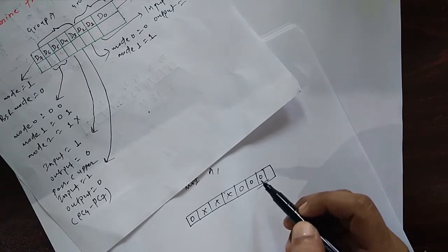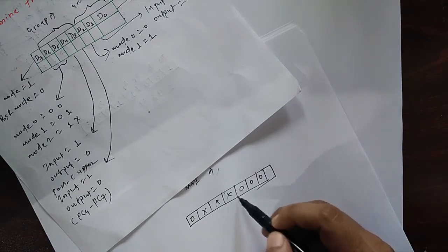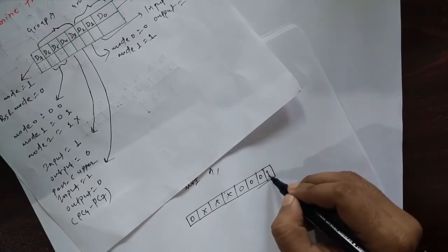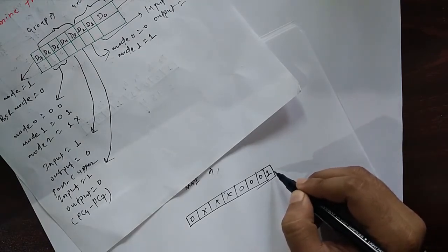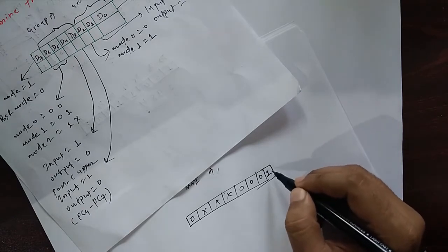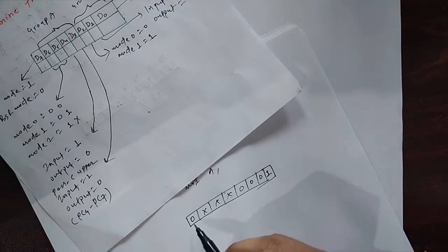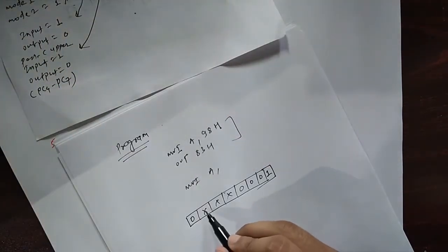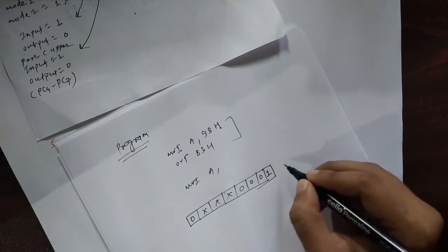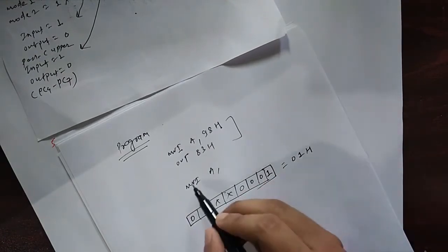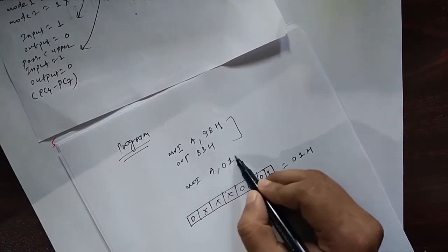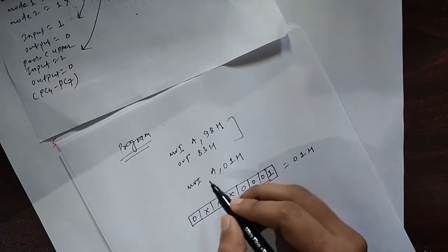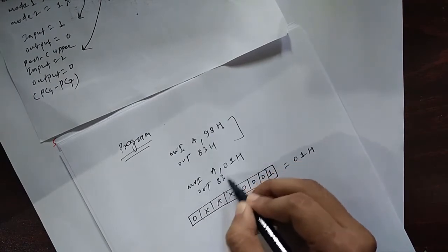So now I guess you have an idea what to write in these 3 fields. And if you are setting, then we write 1, otherwise 0. If we are resetting, then we write 0 here. So this is the control word for setting PC naught. If we consider don't care as 0, then this will be 01H. So MVI A, 01H, and then we need to output it from control register, so OUT 83H.